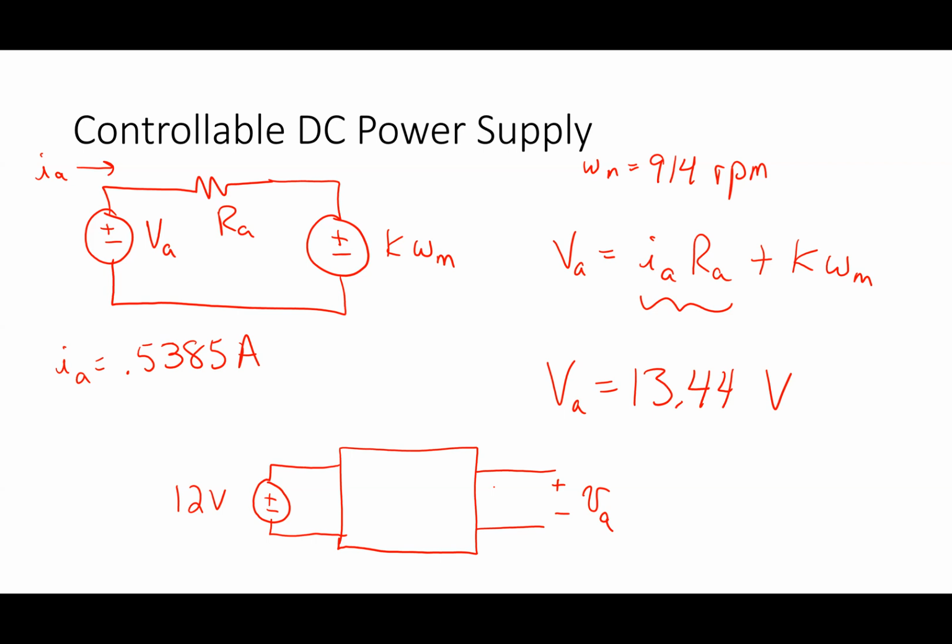Zero. If I put 10 volts AC on one side of a transformer, the turns ratio tells me what's on the other side. But that was all predicated on Faraday's law. I had to have a changing magnetic field passing through the other coil. If I have a DC current and a DC voltage source, there is no changing magnetic field. The magnetic field from a DC current is going to be constant. So there is no way to get a transformer to work here. A transformer is nice though because it's very highly efficient. We did that. The efficiencies were 90+%, very high.